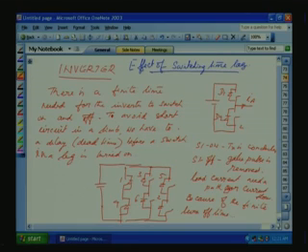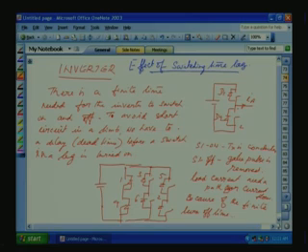The moment this is turned on, the current IA will start decreasing, but current cannot change instantaneously. So this load current will force it to come through the diode. In this case, the switching lag time will not have an effect, because the diode will conduct immediately irrespective of whether the transistor is turned on or not.